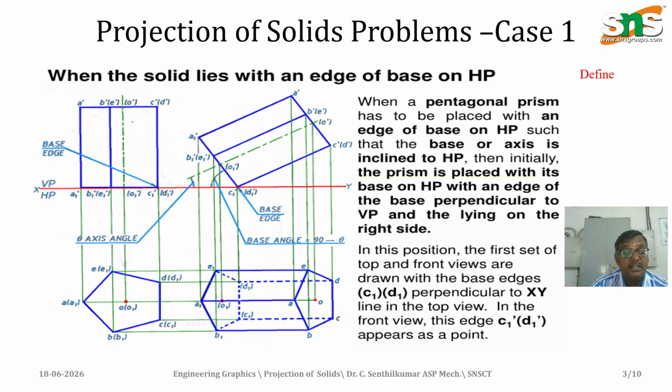Based on 360 divided by 5, we get 72 degrees, so that we can draw the pentagon. We name it A, B, C, D, E, and we name the back side A1, B1, C1, D1 inside the bracket. We project upward. In projecting upward, they will indicate in the problem the height of the pentagonal prism, so for that height we draw it. These edges having the intersection will be drawn in dark lines, as visible lines. These are the visible lines here. This is the center axis line.